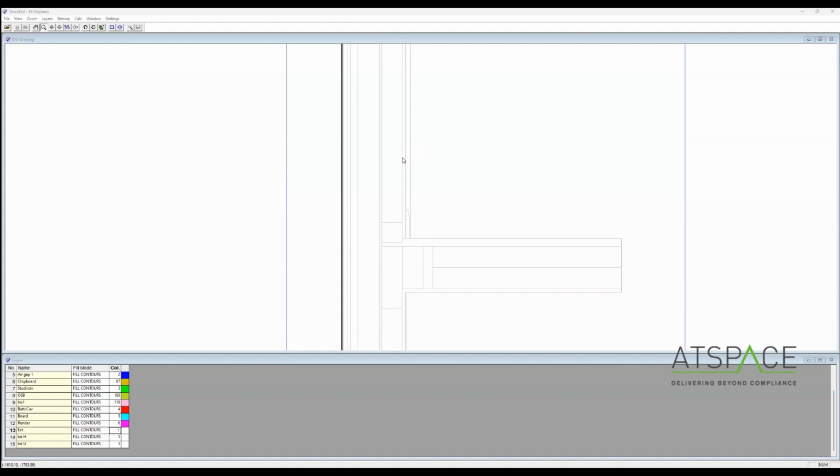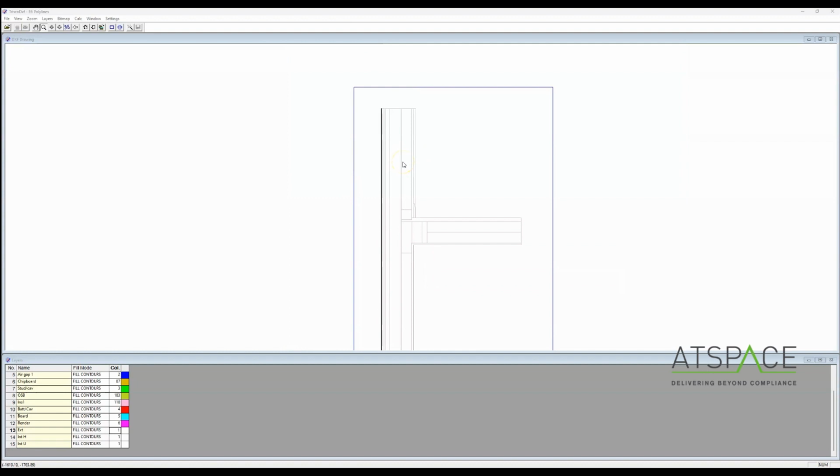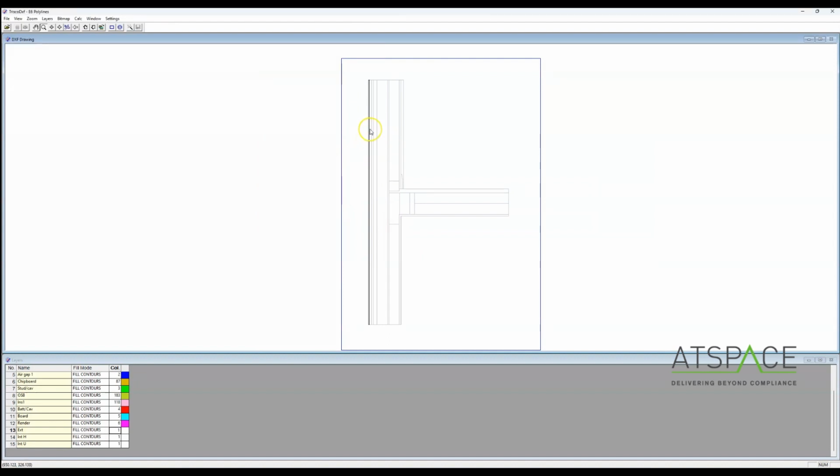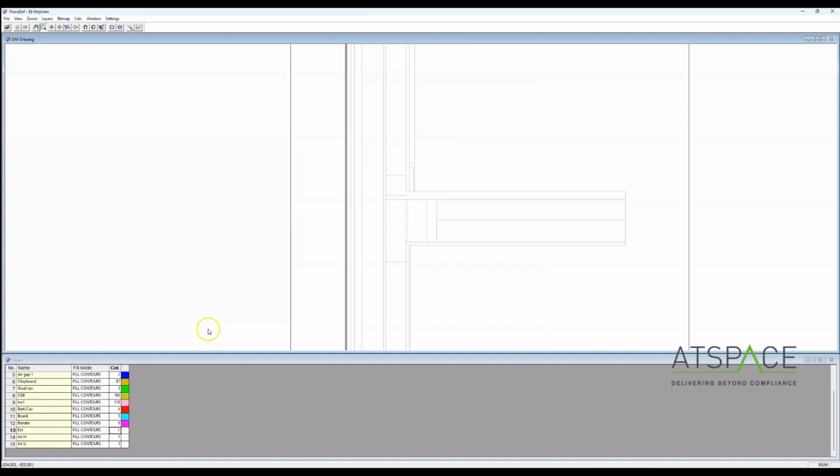Yeah, that's essentially all they are. The boundary conditions is there's different temperatures which different exposed surfaces are going to be at. For the internal boundaries, you normally have a temperature of 20 degrees, and then we also do an external boundary condition, which is normally at 0 degrees. That kind of allows the software to simulate the heat flow through that junction, which is obviously the whole purpose of figuring out how much heat is going to be lost. So yeah, that's why those are included there.